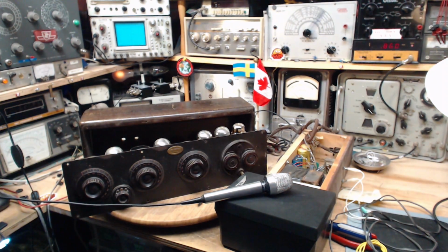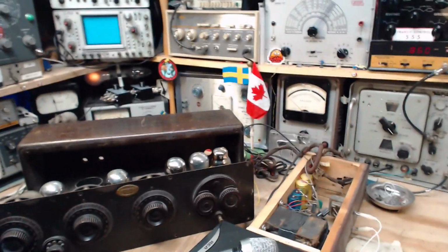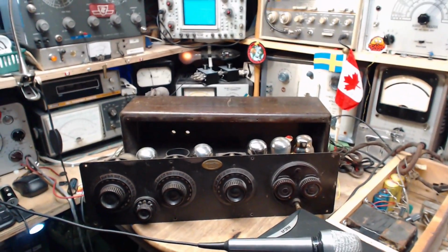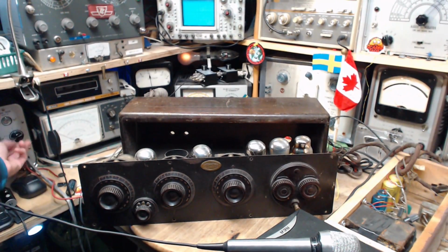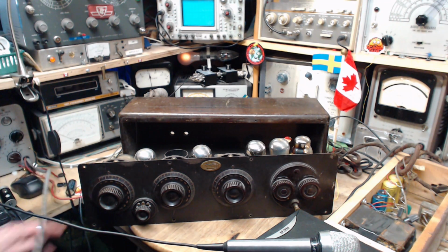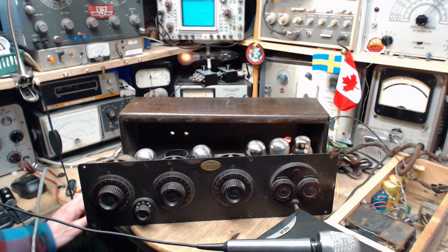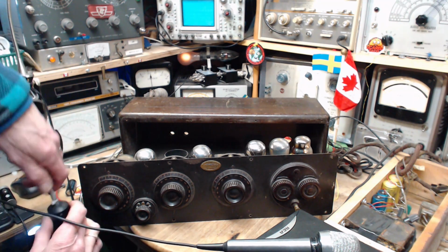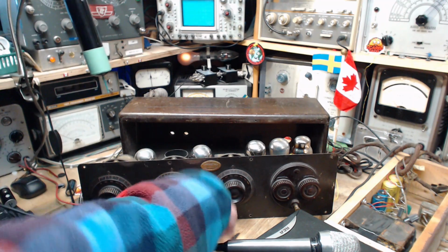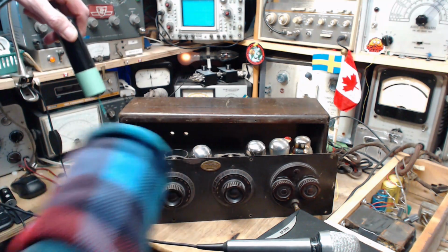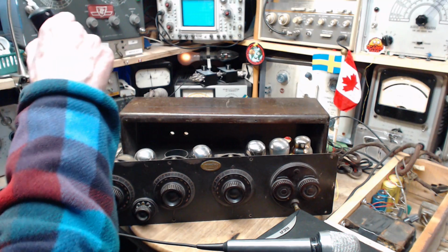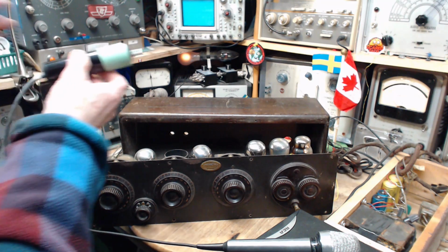What I should do probably is use the signal tracer again and see if anything's different this time. Good idea. Turn it on. I'm using the signal tracer with the ground wire disconnected, which is a little bit weird. It's just laying here on the bench. Now you can hear every little... Ooh.